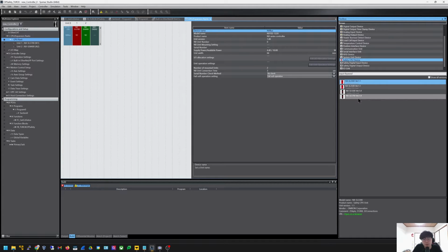It only shows version 1.4, but for example, if you get the device from OMRON, maybe they cannot provide the latest version of the safety CPU device for you. If you configure the module as V1.4 but your hardware is 1.3, you cannot use it. So you need to click show all versions and configure exactly the same version in your configurations. It's very important.